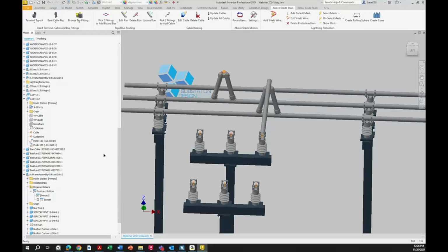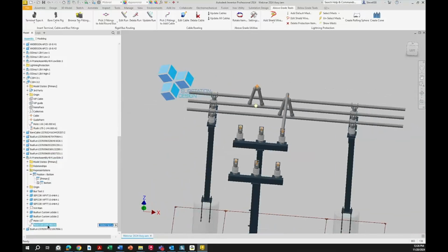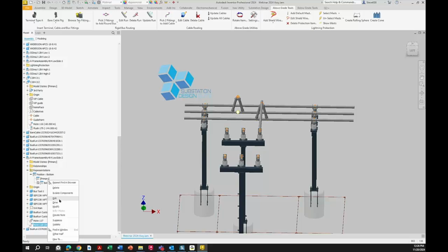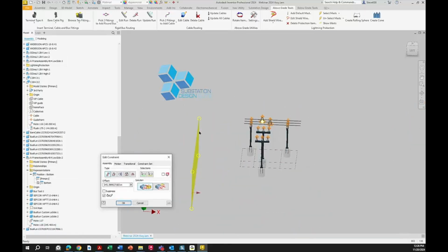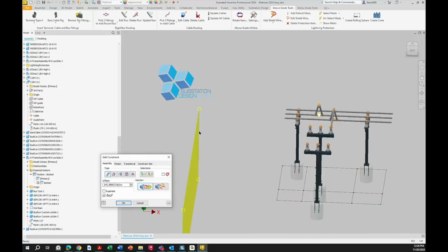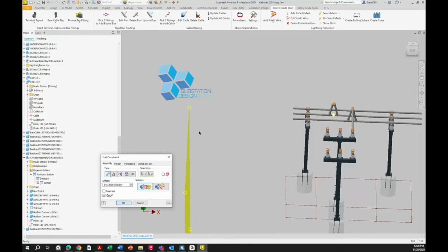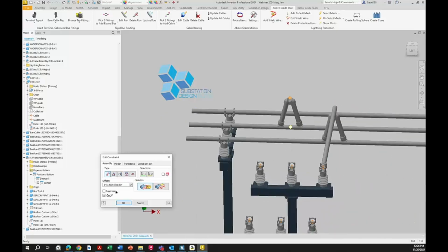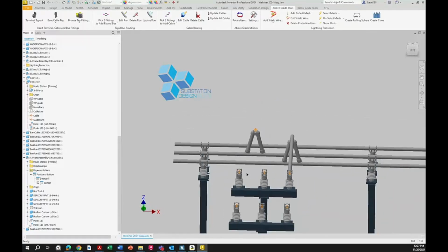So I'm going to go back to this tool, and I'm going to look at my offset here. So my offset, if I edit that, it's working off of this plane here. So this is the plane it recognized to place that pipe, and that's where it's placed it. So it's 345.399, whatever it is. So it's garbage number, but that is the number we have, right? So what I want to do is I want to move it in line here.